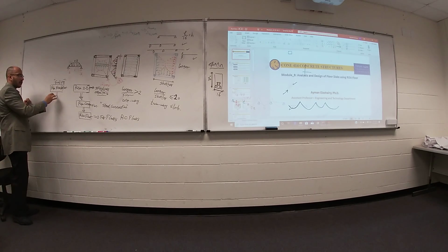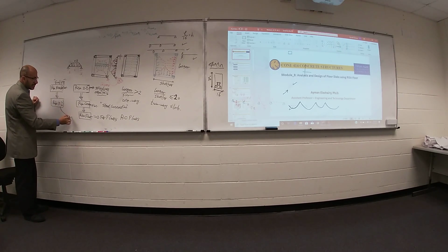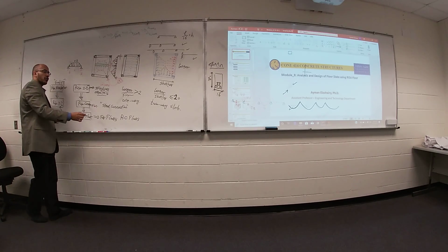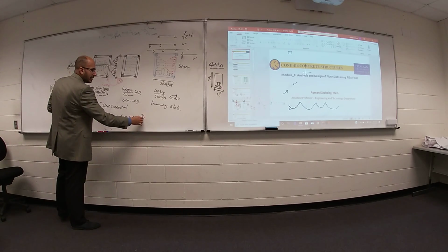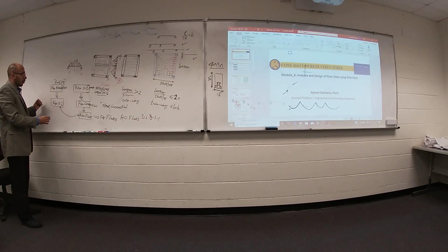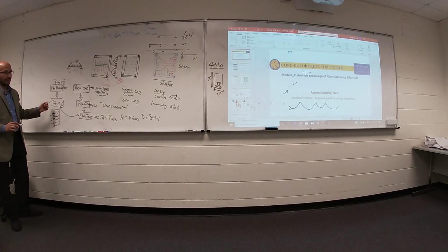Okay, there is another one called RISA 3D. RISA 3D is connected to RISA Floor. This one just solves your floor slab due to dead load and live load. But RISA 3D will solve your building as a 3D building with floors to consider your lateral load, earthquake and wind load. This one is more advanced.